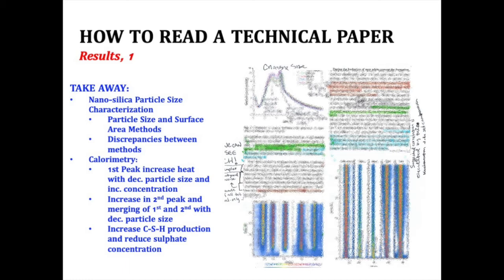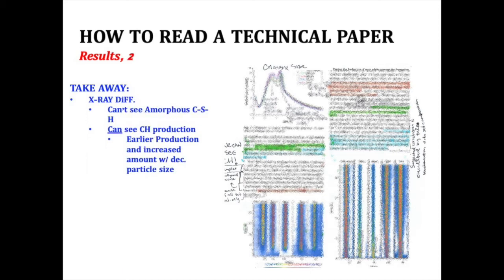It's great that we're looking at calorimetry, but we have no other measurable method to look at the calcium silicate hydrate production because it is an amorphous crystal, so we don't get diffraction patterns like we would out of a repeating lattice structure. In comes X-ray diffraction, where we still can't see that amorphous calcium silicate hydrate, but we can see that crystalline